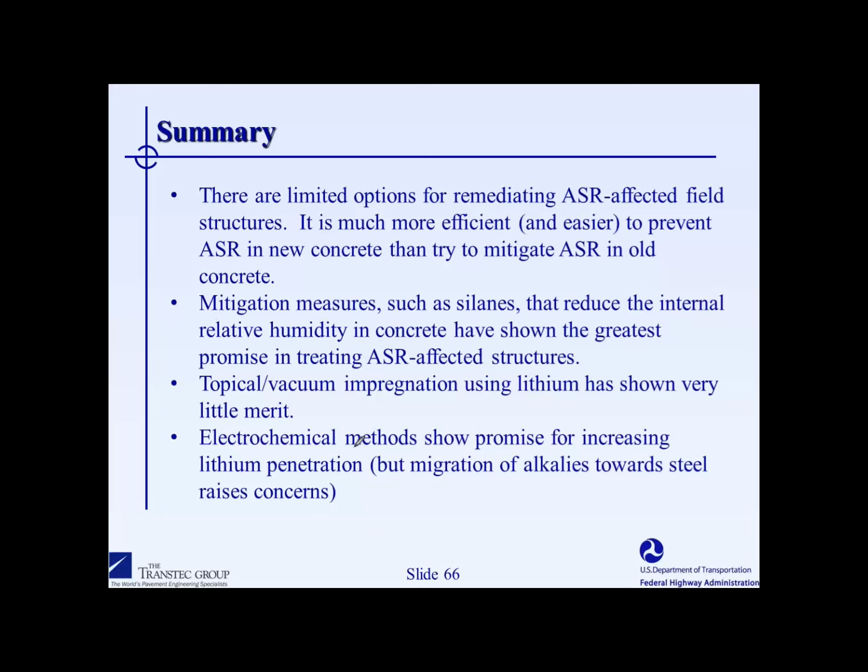But our experience is it's typically 1 gallon for every 125 to 150 square feet. That tends to be pretty consistent across most of the silanes that we've looked at. And we already discussed the issue of reapplication, but first of all, refer to the manufacturer's recommendation. Our experience has been somewhere in that range of 1 gallon per 125 to 150 square feet.